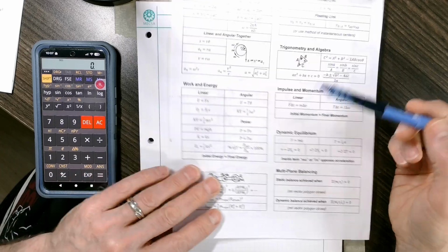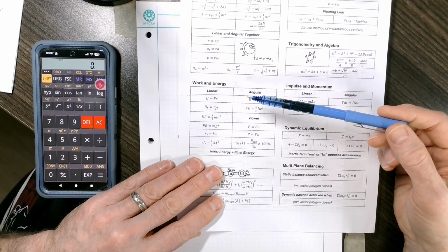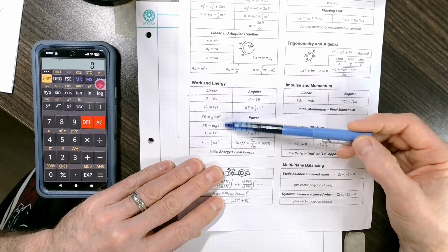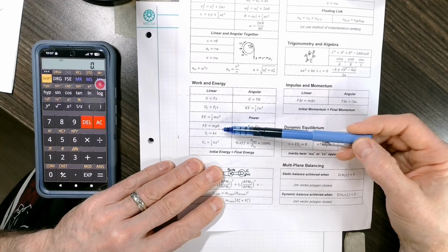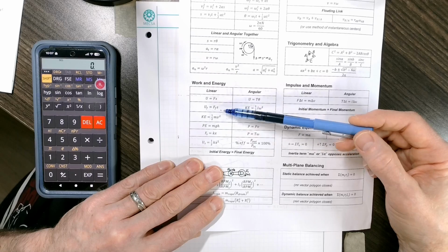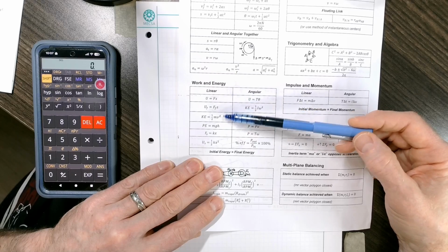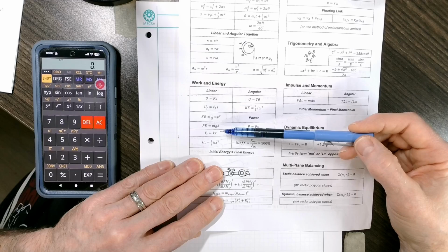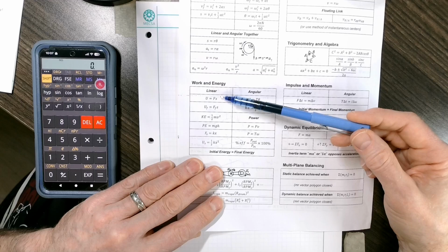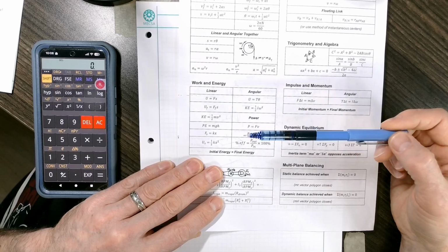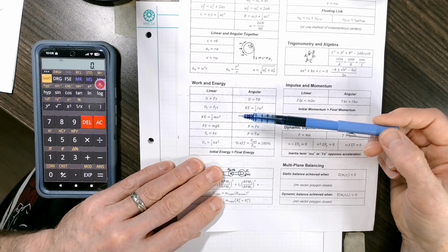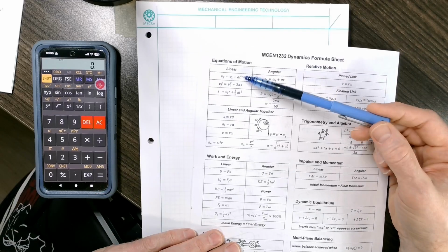Likewise, if you have a problem or a collection of data that includes velocity and displacement, but not time and acceleration, then the energy method is a nice fit, because its currency is displacement and velocity. Now you think to yourself, well, that's great, but what if I have these inputs, displacement and velocity, and I want acceleration? Well, the link to all that is kinematic analysis, which is the equations of linear motion.